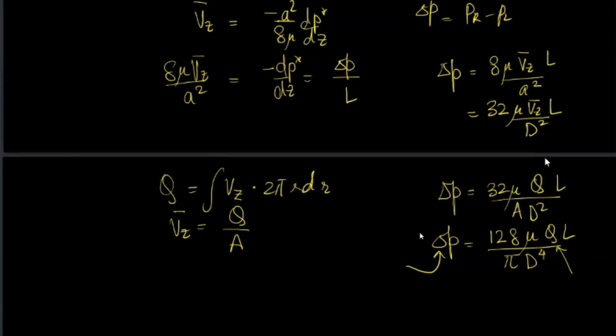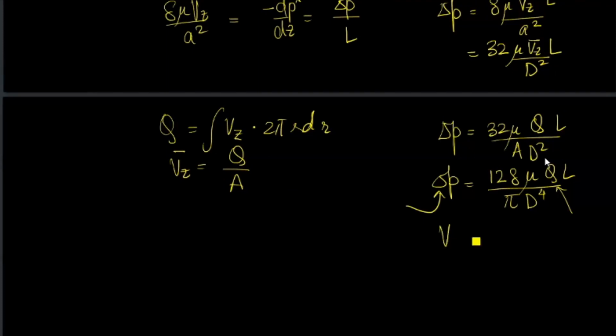It is quite analogous to the electrical circuit where V equals IR. I is the current and it is like the volume flow rate, V is the potential difference and it is like the driving pressure gradient. So the hydraulic resistance, if I write L over here and Q over here, this entire thing is like the hydraulic resistance.